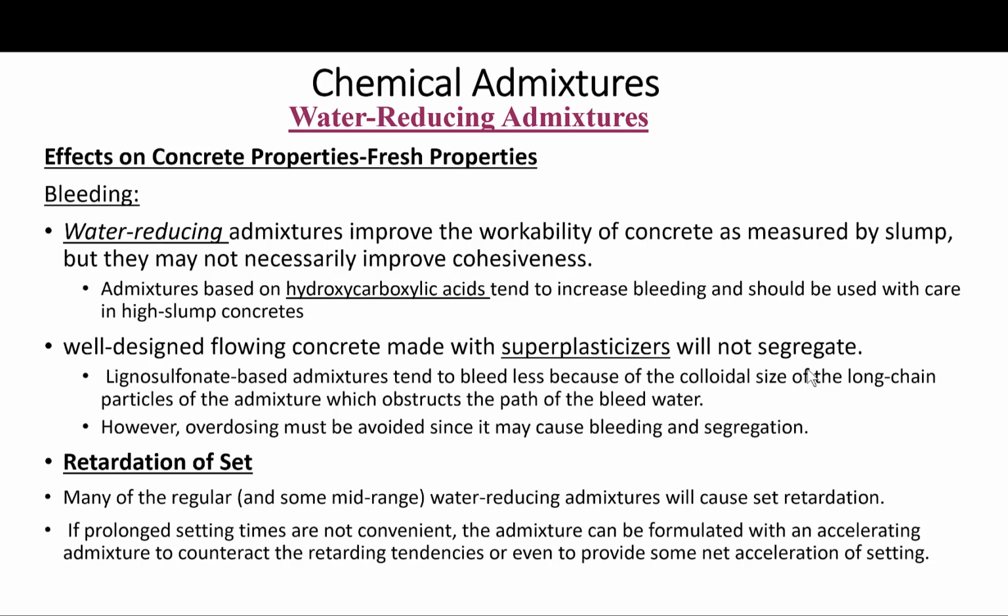Okay, so again, manipulating the times of addition, planning them correctly, testing your admixtures and the interactions with other admixtures allows you to make any adjustments to the concrete mix, to the dosage, to the time of addition, all before you are actually ready to pour whatever concrete members you are trying to pour. All this has to be done before.